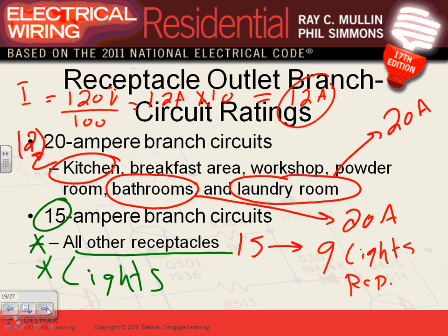So you can put 10 lights on if the lights are 100 watt. And most of us right now are moving to less, 75 watt, and compact fluorescent is even less, 23 watt now. So that's why I thought when you go up to 9 lights, guys, you're good. Shall we do that for our design? Nine. Really, in reality, you can almost throw 15 on it and move on. Nine lights or receptacles for convenience, unless you're told otherwise. Questions about that? So we know how to circuit. Start throwing receptacles up to 9 on one circuit. Ten, split 5-5.